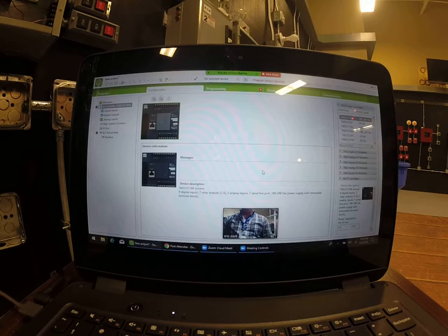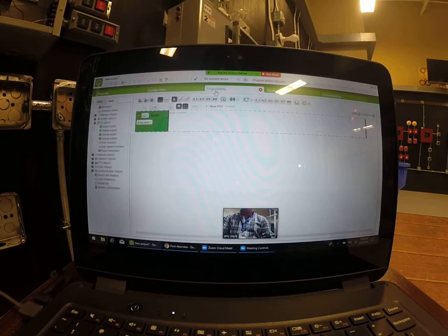Now that the PLC is picked, we can then go to programming. So if you look at the top of your screen, you'll see an icon that says programming. We'll click on that. Now, just to get through some of these basic programs, we're going to go pretty quick and get to the other features later. So, PLC doesn't see push buttons. It doesn't see switches. All it sees are open and closed contacts of various forms.